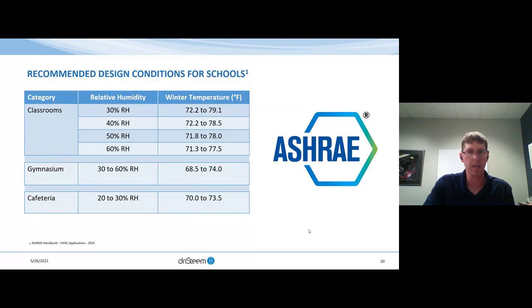And that concept of thermal comfort we just discussed, now you can directly see if you maintain that relative humidity at a higher level, you can see the direct recommendation in terms of dry bulb temperature being reduced. So by putting more moisture into the space, you can drop that temperature set point. And this just shows that same thing. And so you can see there's an ideal range for a number of these spaces.